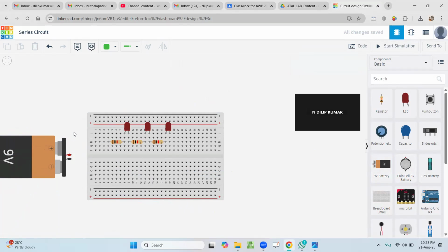In order to connect the battery, breadboard, and the LED resistors, you need a wire. For that, place the mouse pointer on the positive terminal of the battery, click it and move the position such that you go for vertical and horizontal motions only, as the wire should be linear in shape. There should not be any cross wiring. So connect here so that this horizontal rail has been completely shorted with the positive supply.